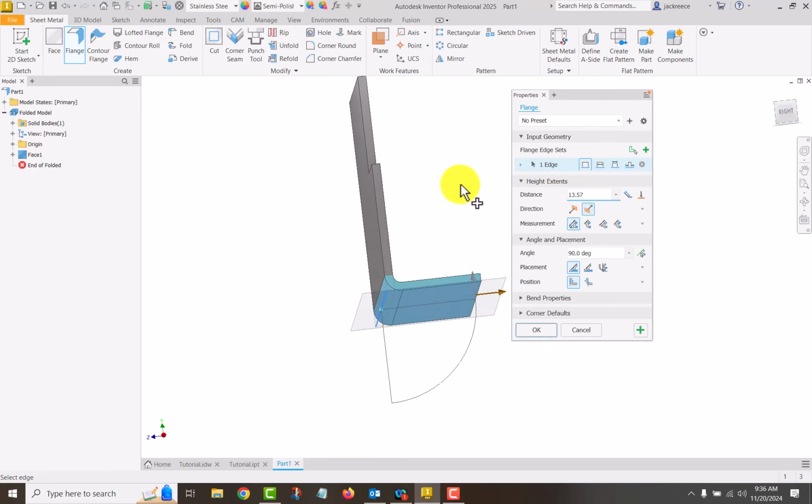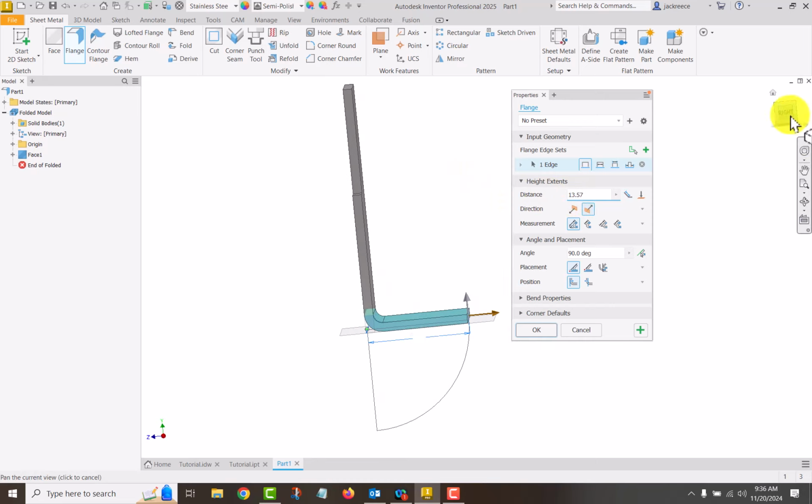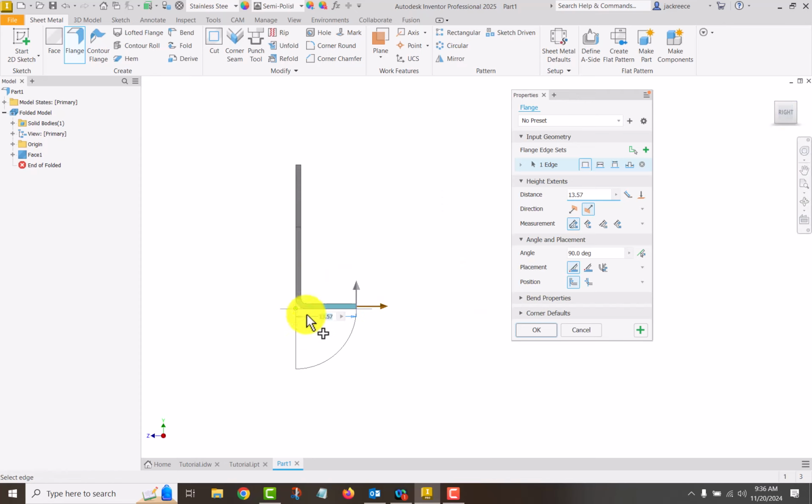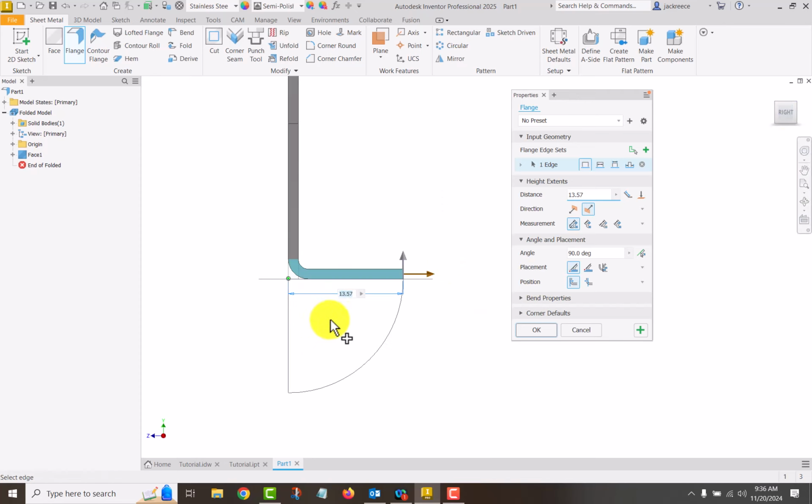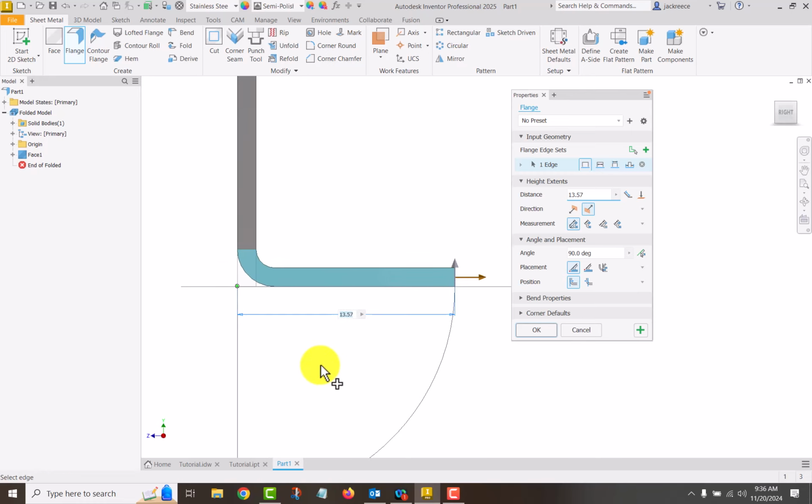Okay, and so now that I've got it in here, I want to show you some of these options. As you work through the bend radius calculations, you'll see that however the part is dimensioned, from what face it's dimensioned, whether it's the outside face, the inside face, the radius point, or maybe the point of intersection of the planes, that's the option that we choose here.